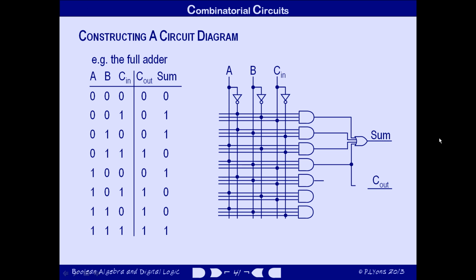There's nothing wrong with doing this. It doesn't overload the electronics, for example. Gates are usually designed so that their outputs can drive 10 standard inputs, which is plenty for most situations. If you ever needed to drive more inputs than that, you'd incorporate a buffer device in your circuit. But we're not really concerned in this course with that sort of real-world detail. We're more interested in the underlying principles. So that's the end of our full adder module.